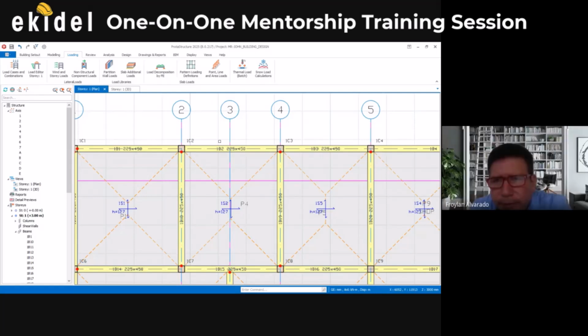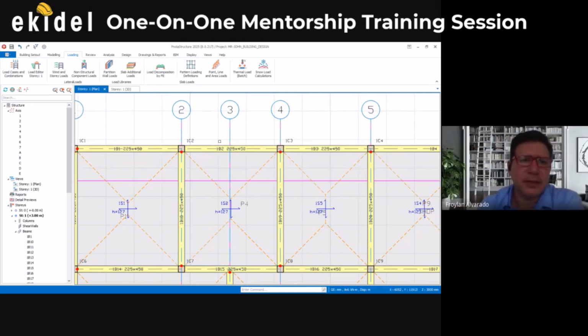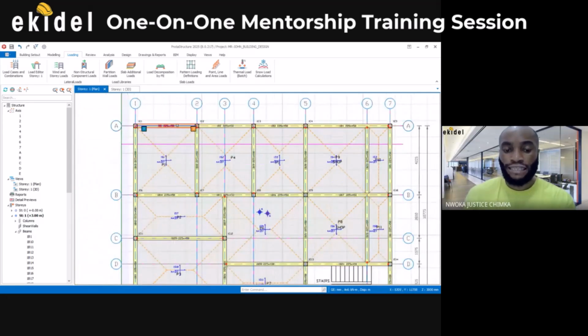But if it's just a minor building that does not require any lateral load, you can choose to apply hinge at the end. Makes sense.